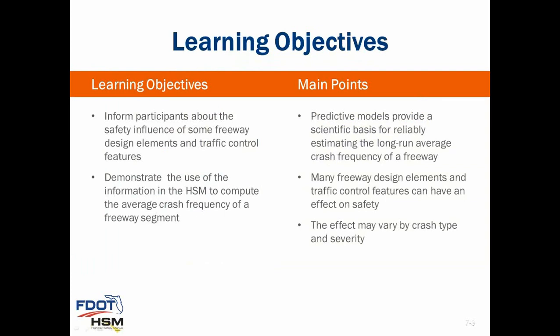There are 2 learning objectives for this webinar. One is to inform you about the safety impacts of several freeway design elements and traffic control features. A second objective is to demonstrate the use of the HSM to compute the average crash frequency of a freeway segment.